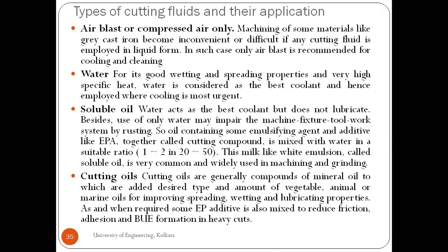That is, air blast and compressed air can be used as a cutting fluid. This air blast is not for lubrication purpose, however, only for cooling and cleaning purpose. Water can be used because it has good wetting and spreading properties, and also water has a very good specific heat capacity, so it is considered as a best coolant.